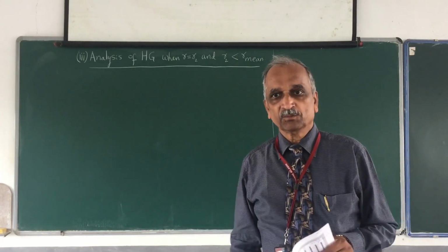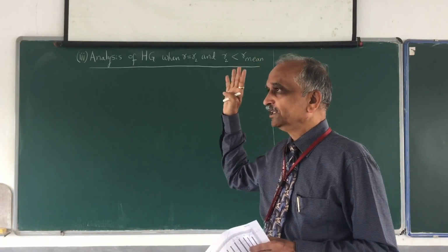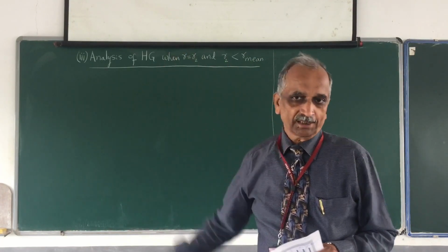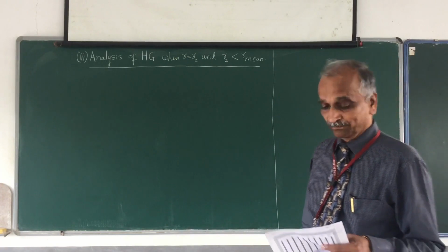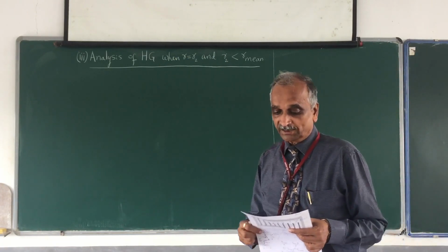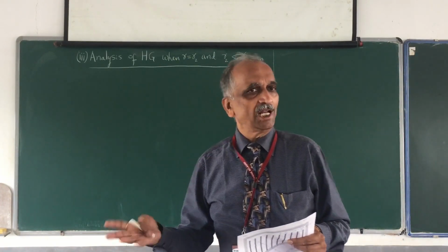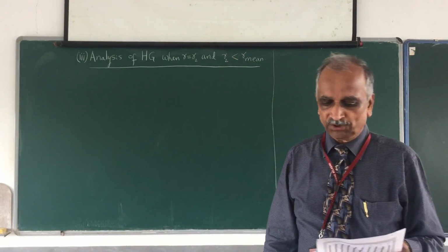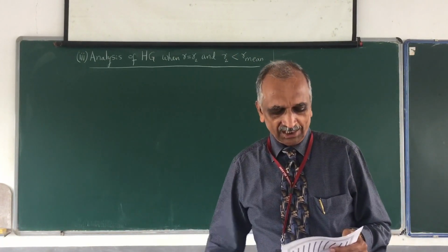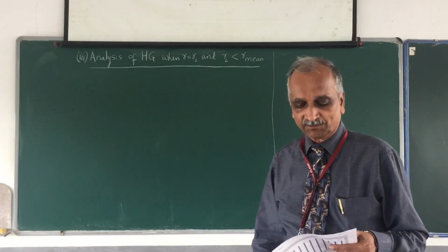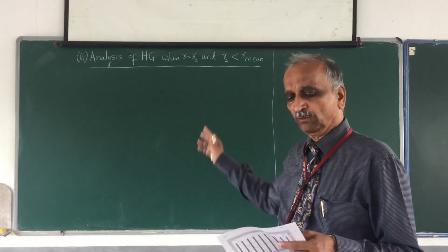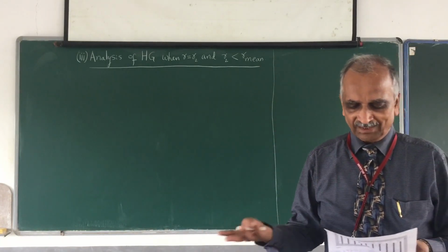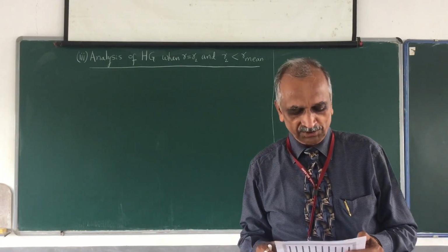Radius of rotation of the balls when the ball arm is vertical, or the ball arm is parallel to the axis of rotation of the spindle. That's what I have called R mean. And R1 and R2 are any two positions in between the minimum and the maximum positions of the sleeve. Then I also have R max. Accordingly, I have different speeds: omega minimum, omega 1, omega 2, omega mean.